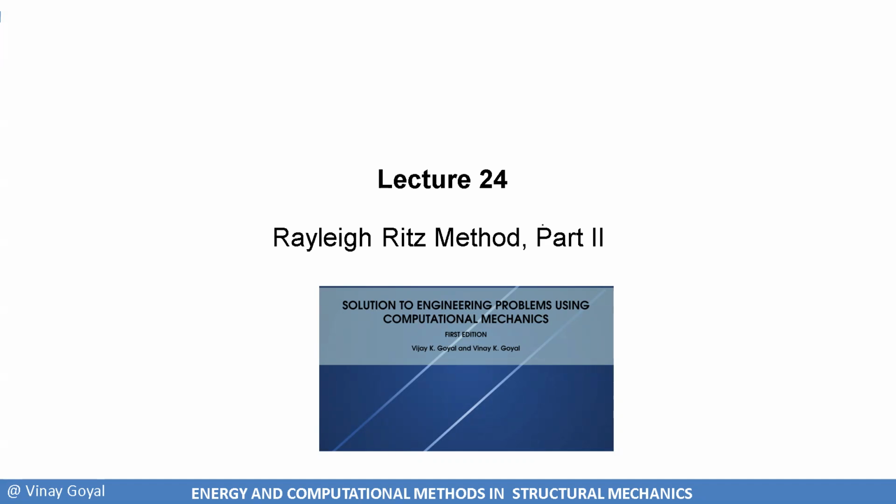Sorry, I have an elastic deformation, so when I remove the loads, it goes back to the original configuration. Secondly, what we did there was to then derive... The second assumption was that the loads are conservative, meaning the loads do not depend on the deflections. So when you make those two assumptions, you arrive at the total potential energy.